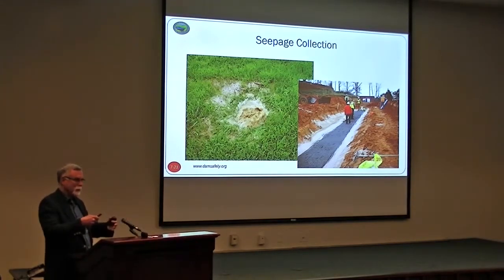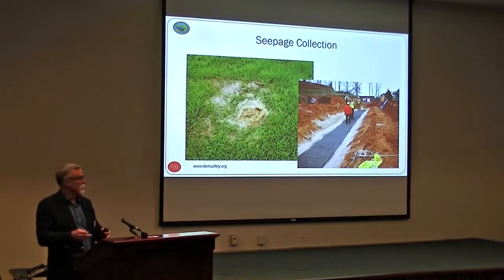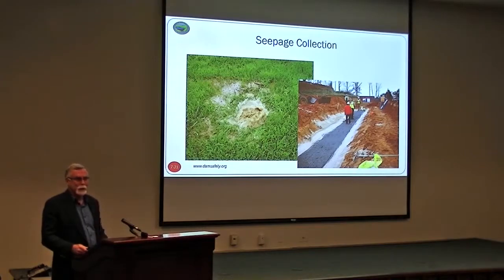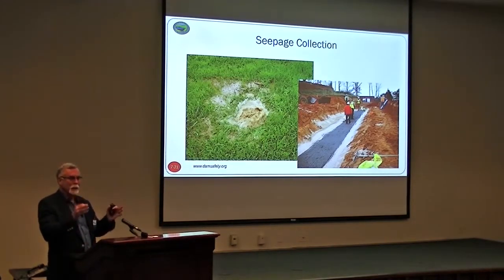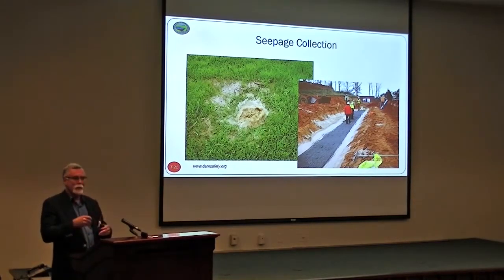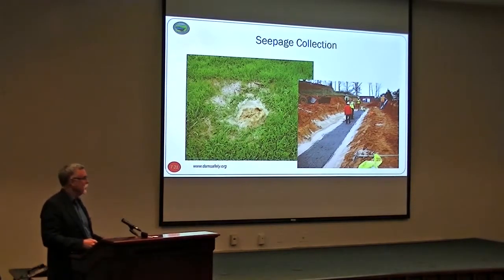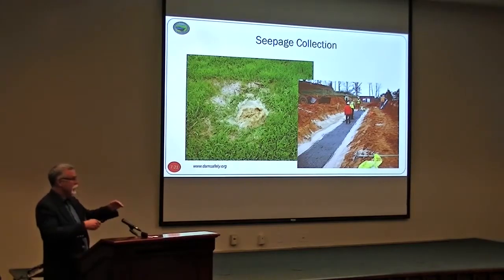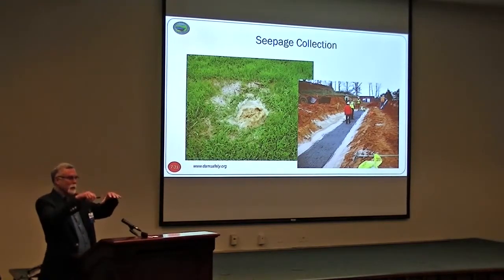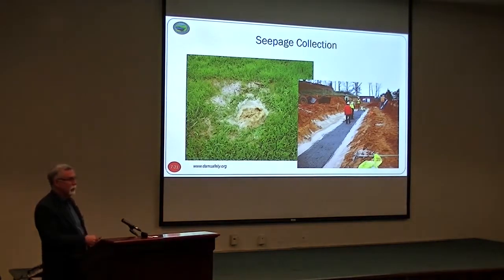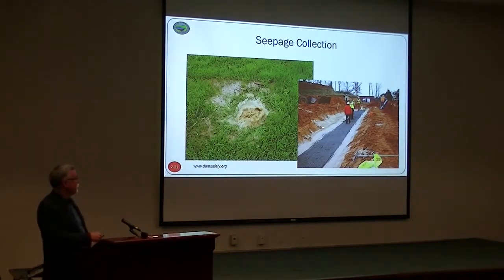And then the soil can't get into the gravel because the filter cloth, like I said, it's a filter. That works great for a few years. Eventually that filter cloth becomes clogged and the water can't get to the gravel. So you may have a drain that's flowing 5 gallons a minute for 5 years and it will slowly start decreasing down to nothing. We did some dam rehab where we dug down to the top of the filter cloth and water was ponded on top of the filter cloth, but not getting through into the ground. So this is the proper way, more expensive, but this will last a very long time, but the filter cloth will not.